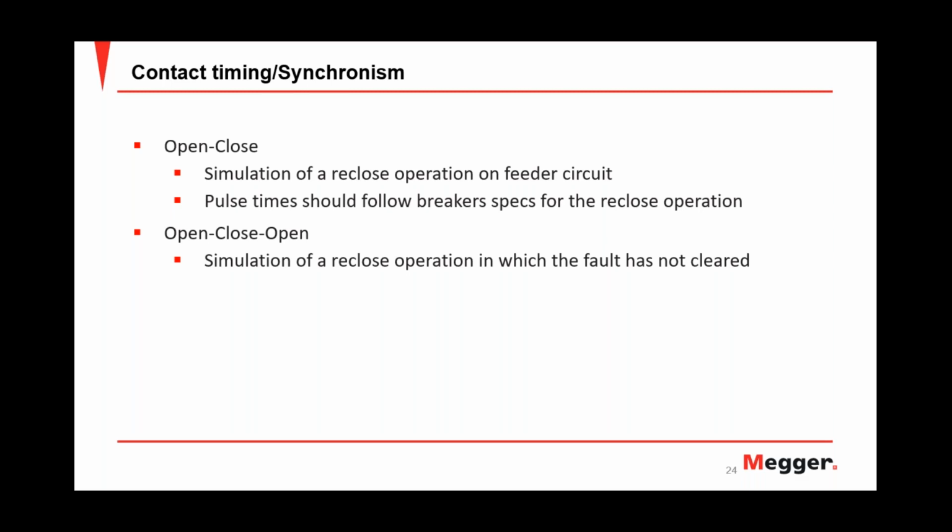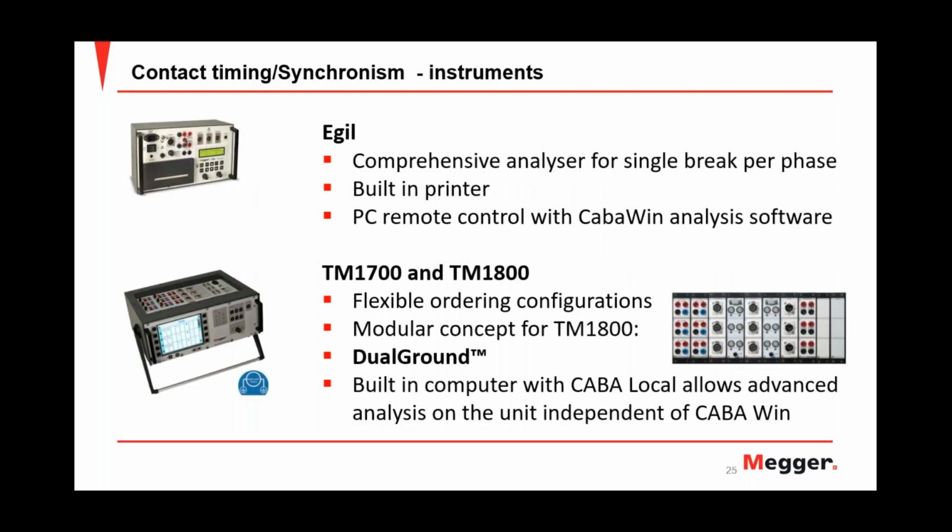That needs flexibility in configuration of your test instrument. And a slightly more complex open-close-open operation can be performed to simulate a reclose operation for which the fault has not been cleared. So contact timing is quite challenging, but we do have a number of test instruments, from very simple, focused on single break per phase.